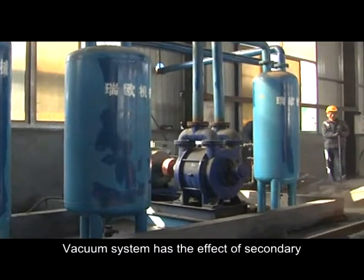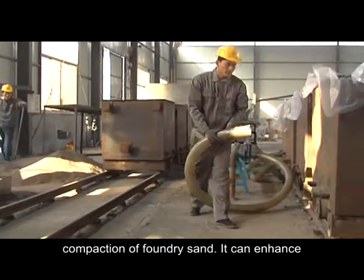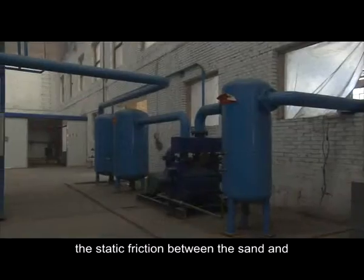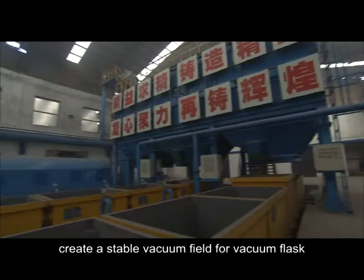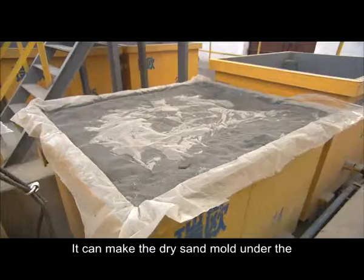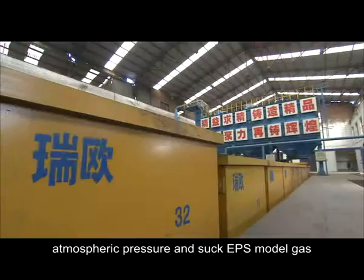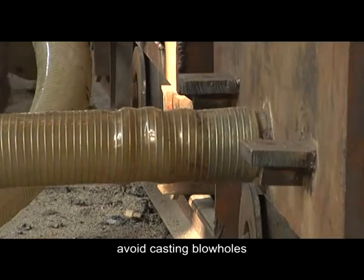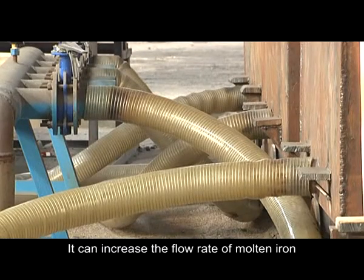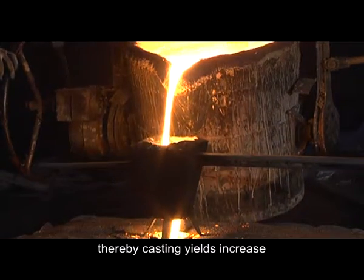Vacuum system has the effect of secondary compaction of foundry sand. It can enhance the static friction between the sand and create a stable vacuum field for the vacuum flask. It can make the dry sand compact under the atmospheric pressure and suck the EPS model gas produced by gasification in order to avoid casting blowholes. It can increase the flow rate of molten iron and the speed of punching, thereby increasing casting yield.